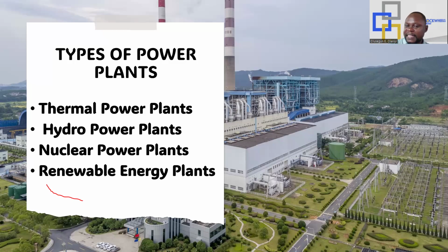Now, the boiler boils fuels to produce steam, while the turbine is driven by the steam that is generated by the boiler. The generator converts the mechanical energy from the turbine into electrical energy. And when the steam has gone into the turbine to rotate it, the condenser cools the steam back into water for use again. That's what the condenser does.